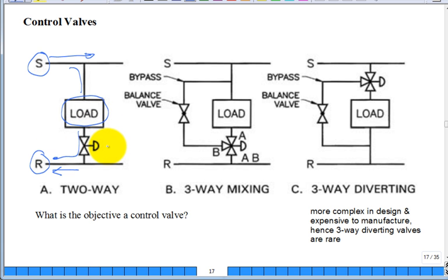So in the heat exchanger, you have what's right here indicated. It's a control valve. Now there's a number of different symbols. So this would be a control valve. If they put a dot in here, it's like a balancing valve. If they put a manual handle out here, it's manually operated. I forget the symbol, but it's all not that important, but it looks like it's pneumatically controlled.